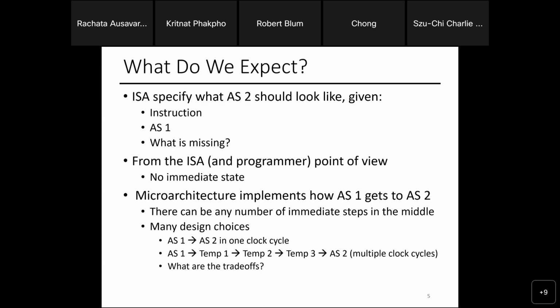So let's say I have 2 types of instruction, the fast one and the slow one. If I clock based on the fast one, what happens? Can I support the slow instruction? No, right? Because by the time I clock, I lose data already. I haven't finished that. So in that case, the clock will be as fast as the slowest instruction.